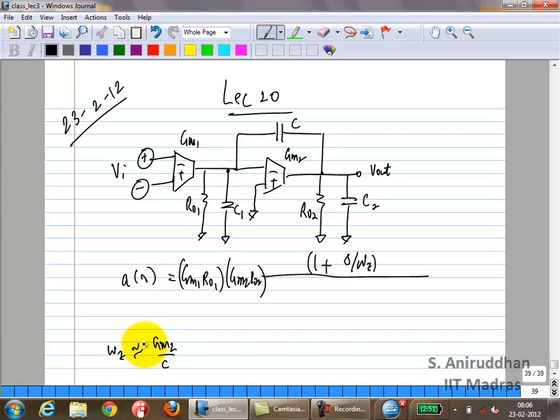Because you have 3 capacitors in a loop, and there are only 2 state variables, because you can't have independent voltages. So 2 poles, and I'll write it as S squared plus S times something plus some constant, or in this case plus 1. I want you to go back home and calculate the actual exact expression. It's a fairly simple system.